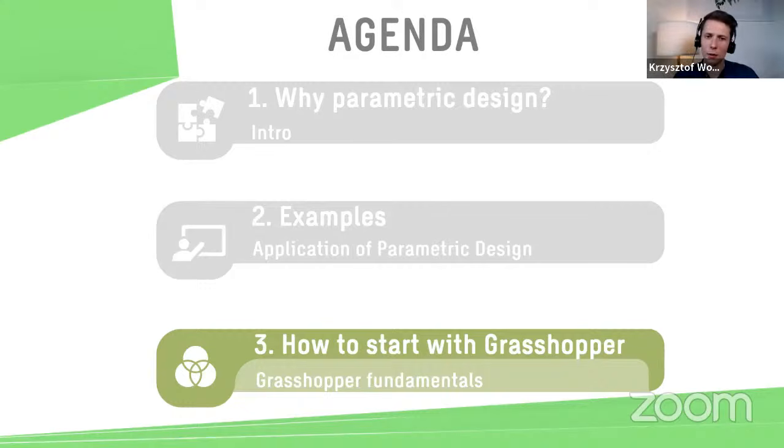Actually, our principle here was to deliver to the site a clash-free IFC of the rebar, and we got it. Of course, there were maybe some small clashes with pre-stressing cables, because there is a really difficult geometry, and you cannot just sit there and try to fix all the clashes. However, we delivered the whole module as clash-free, because it saves a lot of time at the construction site.